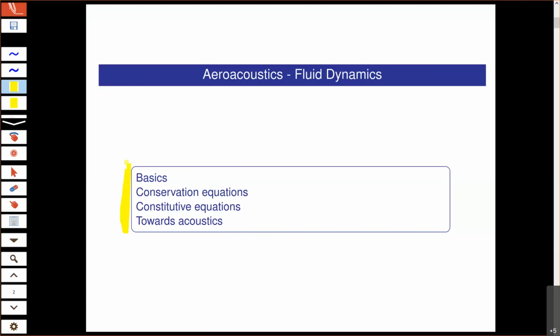So we already also described their acoustic fields, but it's very difficult to decompose such compressible results, as the pressure or the velocity or the density, into the fluid dynamic part, which we mainly call the vortical part because we have vorticities there, and the longitudinal part, which is a part of the compressible quantity, which will go towards acoustics.